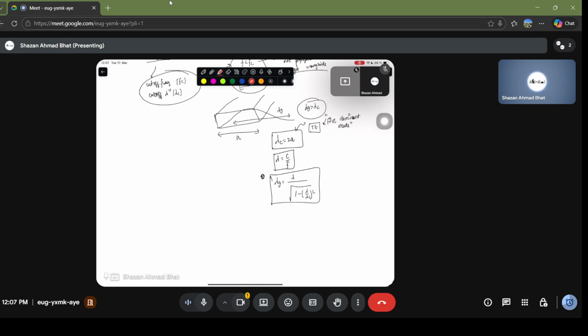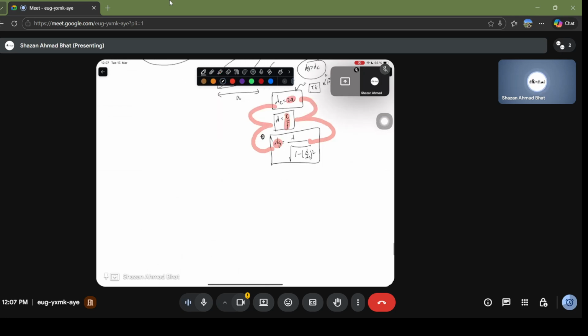And if you want, you have to calculate this, and this, and then this, and you compare these three quantities in order to understand whether your wavelength is greater than the critical wavelength or less than it. But you always need to compare the cutoff wavelength with the wavelength inside the waveguide, and not this wavelength, because this is the wavelength in free space, out of the waveguide.